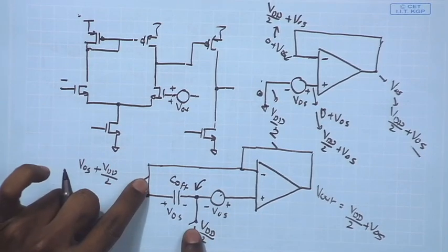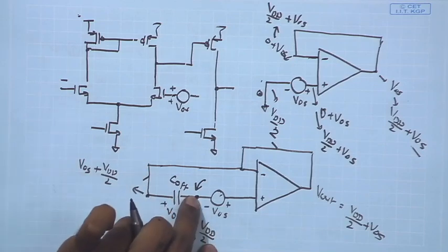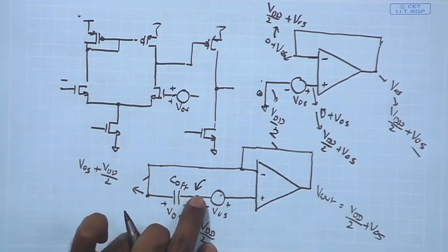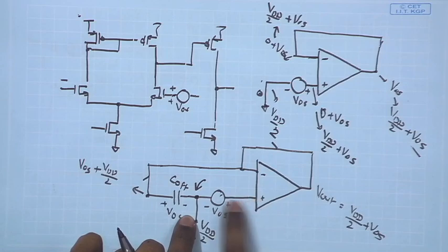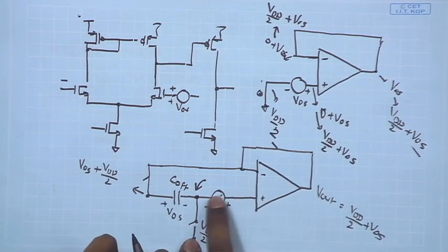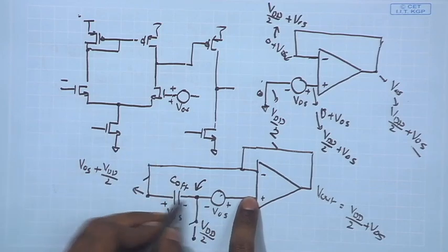So, if I assume that these two switches are opened simultaneously, after that this node becomes a floating node, because it does not have any current path through any other transistor. This is the input device, MOSFET gate. Ideally, it is having very large impedance. There may be some gate leakage current, a small amount, we can assume that it is very small, and this is the capacitor.